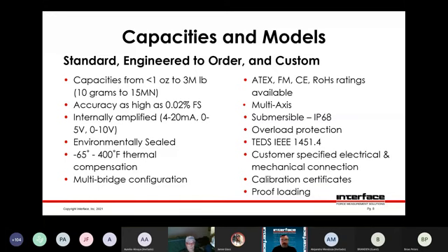The signals, as we discussed earlier, are millivolts per volt inherently, but we can provide amplification for 4 to 20 milliamps or 10 volts, whatever you may require. We also have digital output, so USB or Ethernet, we can accommodate all different kinds of signal levels. Some load cells want to be sealed if it's going to be outdoors or submerged under the ocean, for example. Sometimes it's subjected to high temperatures, so that's definitely worth mentioning when you're talking to an application engineer. It's going to be just in a lab at room temperature, or there'll be extended temperature ranges involved.